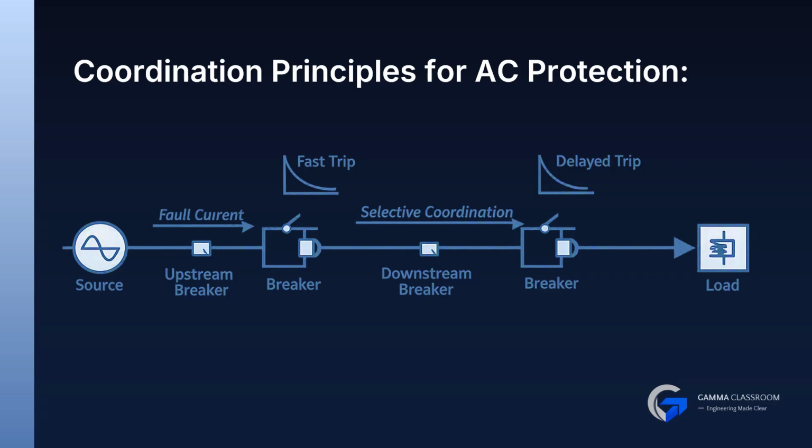Coordination ensures only the nearest device trips. Upstream breakers act as backup, and the time grading prevents overlap between curves.